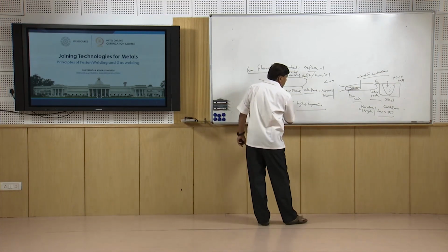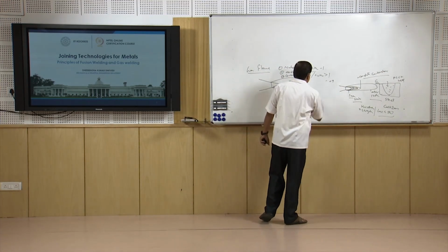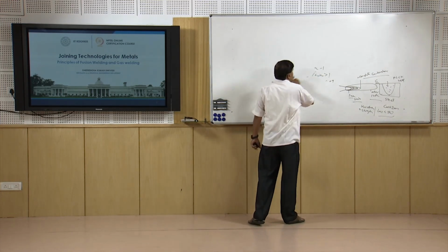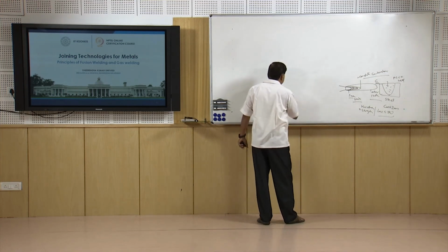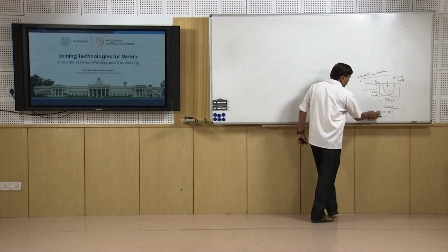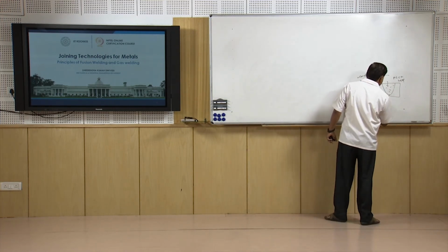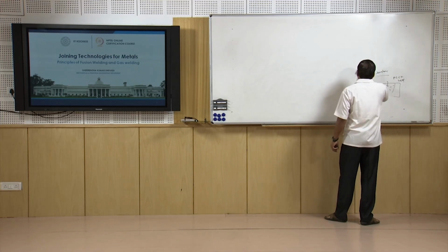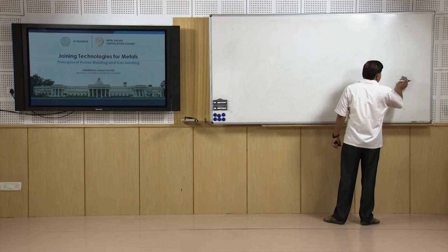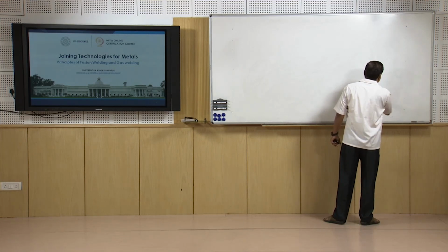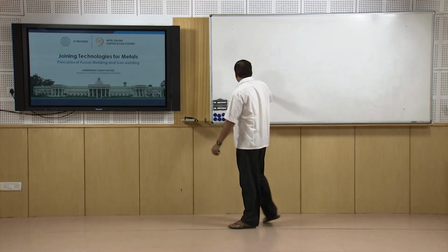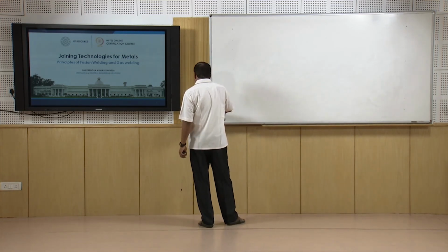So, this is about the different types of flames formed in gas welding. It is preferred to use the neutral flame, where complete combustion of the acetylene and the oxygen takes place during the welding. Sometimes when high resistance and high hardness are required, low carbon steels can be welded using the carburizing flame also.